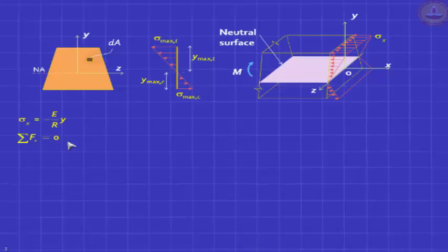That curvature is very small, so we still pretend it's all along the x-axis. But it is stretched and contracted. So if you plug in the value of what is Fx in that element, the Fx is sigma into dA, which we need to integrate across the entire area of the section, and that's what we'll do. So the net axial force, normal force, in this case horizontal force, must be 0.